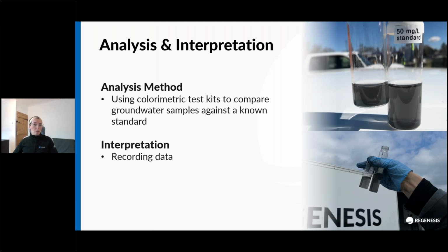We document all of the groundwater parameters during sampling, as well as the recorded concentration of carbon. And this enables us to have confidence in the barrier and to sign up to providing warranties where they are requested by the client. It also enables us to identify whether there have been any issues with achieving that radius of influence, and therefore if any amendments to the design are needed. I'll talk a little bit more about this in a few slides.